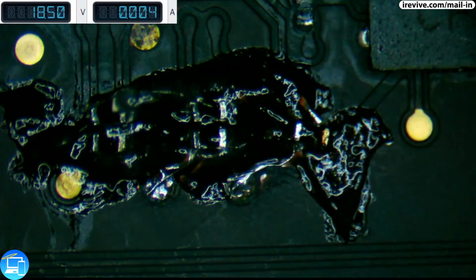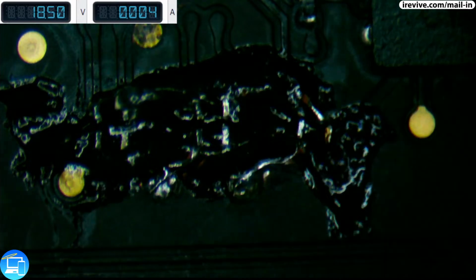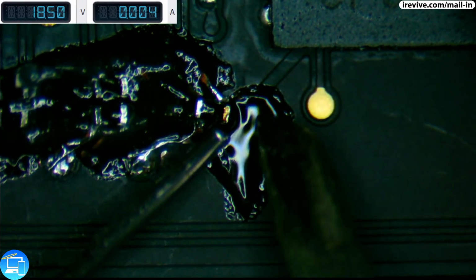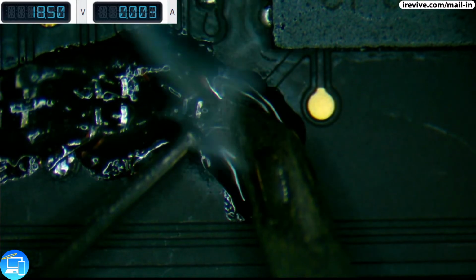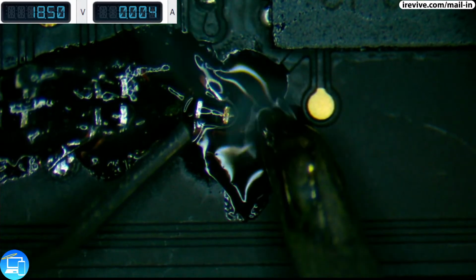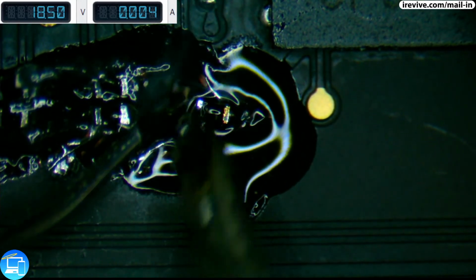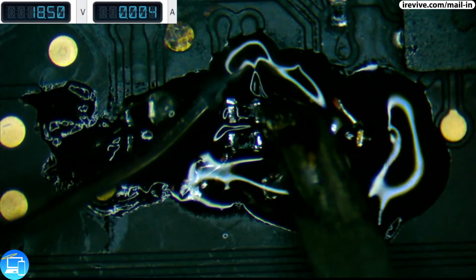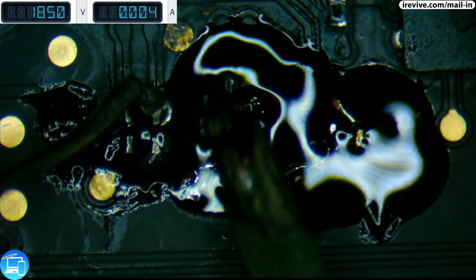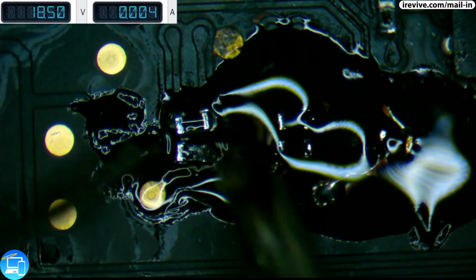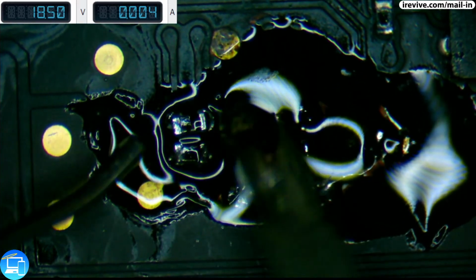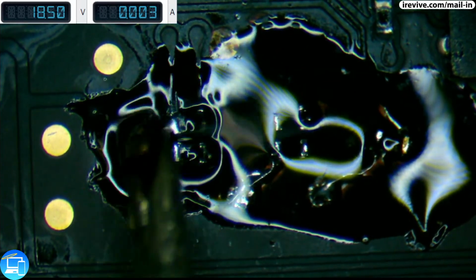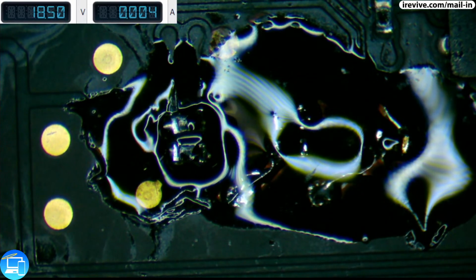This 5th resistor, since it has a via, and it has traces, and I had to run 2 jumper wires, I really want to make sure I have a nice solid connection. So I'm putting more solder there. Same thing here. Let's touch that up some. This resistor could benefit from some more solder. That one seemed okay, but we're just going to touch it up anyways. And because I don't trust my hands. My hands are too shaky today.